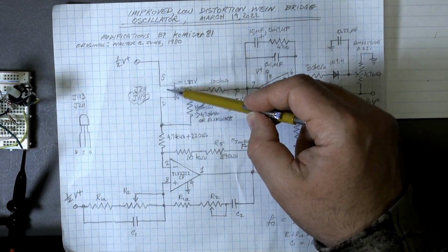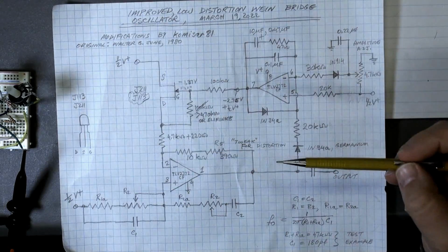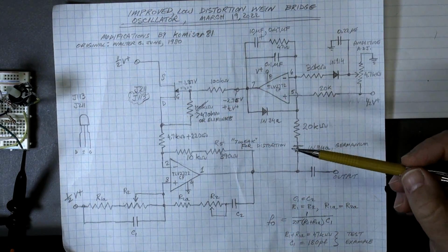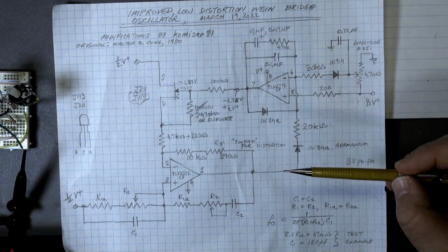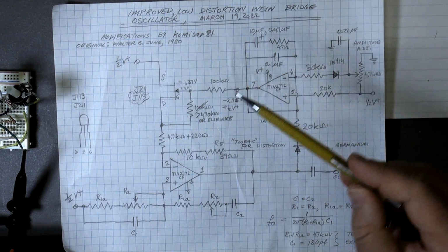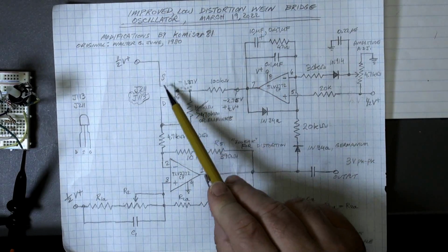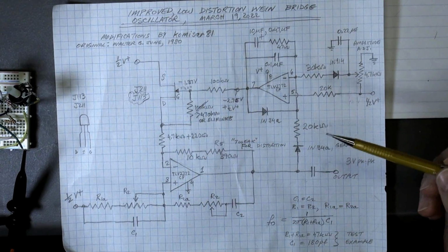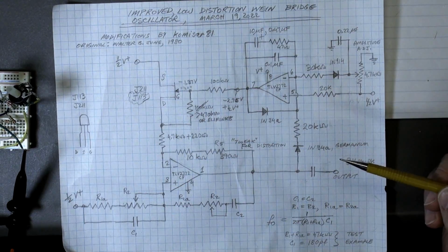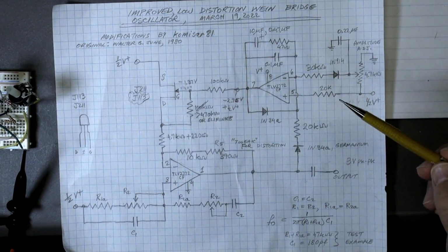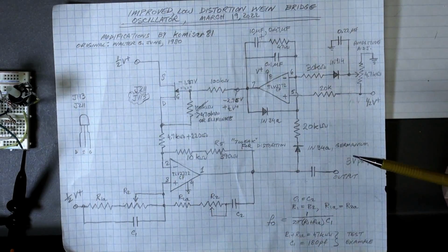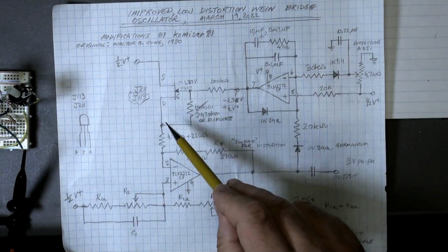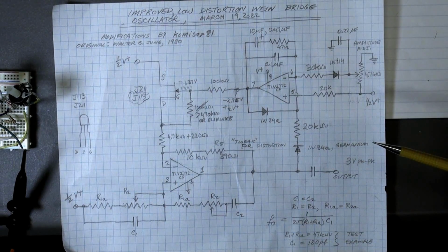So the JFET is a little bit on the nonlinear side. It's a nonlinear device as far as source to drain resistance. So that's where the distortion in the output will originate. It'll come from the nonlinear or voltage dependent drain to source resistance of the JFET. So I can show you the JFET curves, and we're attempting to use this JFET in the lowest possible drain to source voltage region as possible to get the most linear effect out of it. And that's kind of how this works.